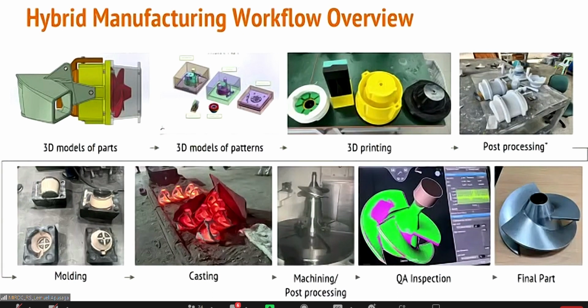Because if you can see the freshly 3D printed parts, you're going to see lines. Since it's made layer by layer, you're going to see the layer lines of the 3D printed part. And those layer lines are going to show in the final part if you don't remove them. At the same time, it's going to make stripping the pattern out of the mold much harder because it causes friction. Okay? And more importantly, bare plastic,